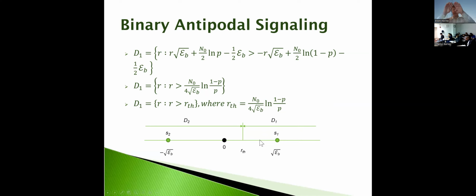So we know that for a Gaussian distribution, those tails go on forever. So there's a finite probability that the noise would push this symbol over here, right? Likewise, there's a Gaussian distribution centered at this energy or amplitude, and its tail is going to leak into this decision area and result in an error.